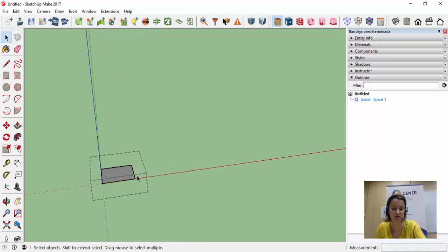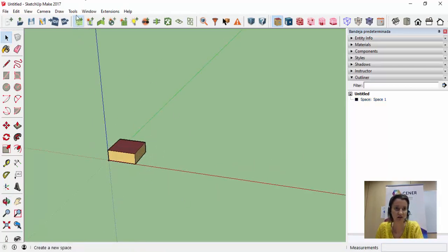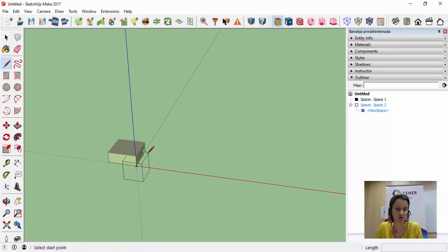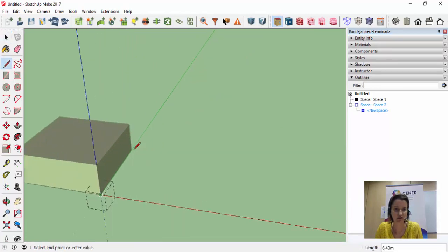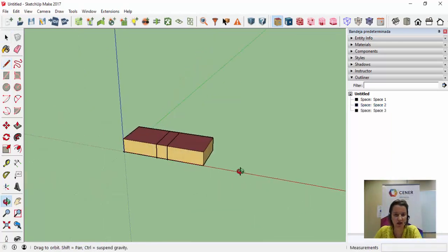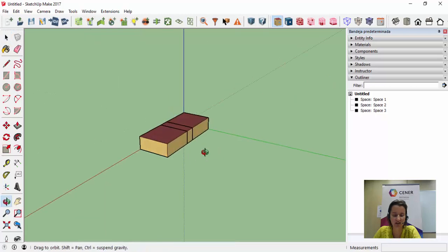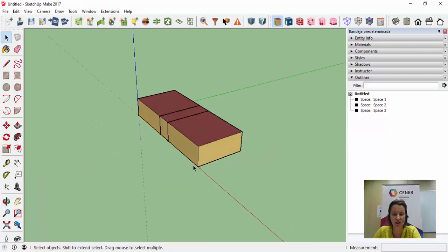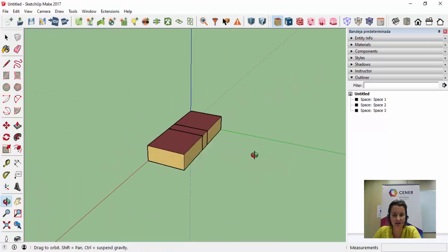As you can see, it's very easy because you can use all the functionalities of SketchUp to do that. The only issue is you need to define each box for the space before drawing any thermal zone. So here we are going to draw the interior zone. Well, when we have drawn the 3 spaces or thermal zones, we can then edit a little bit the envelope.